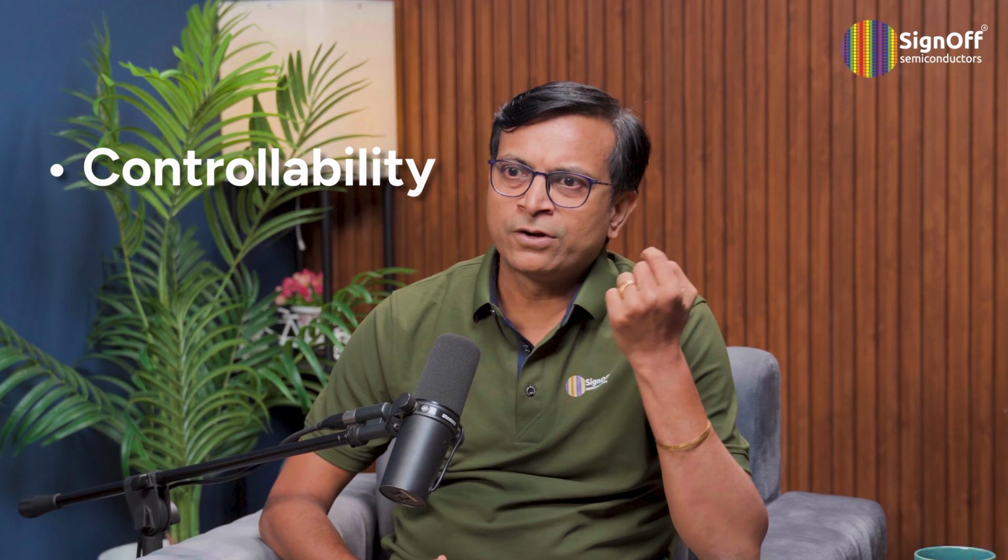So, Rakesh, scan is a very basic element of the DFT architecture. When we do scan chain insertion, we are trying to get two major things out of it. One is controllability. We want to control the design the way we want. For that, we have to push data inside the chip and make sure that the full design is under our control. The second thing is, once you give the inputs and controls to the design, you want to capture how the design is behaving and observe that response, which is called observability.